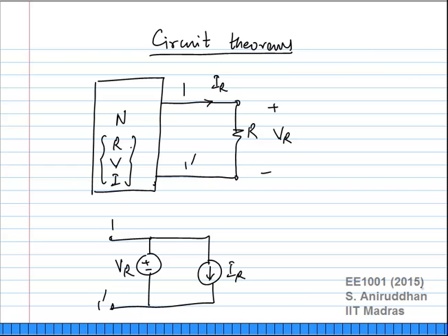Why not? It can be a current through the voltage source. What is this equivalent to? A voltage source in parallel with an IR. Near VR, we can add another current source, but it will have zero current. But that's just a wire. Or it's actually an open circuit, sorry. A current source with zero current is an open circuit. We have seen this before. Now what is this? First of all, let's finish this and then we can come to other suggestions. What is this equivalent to?